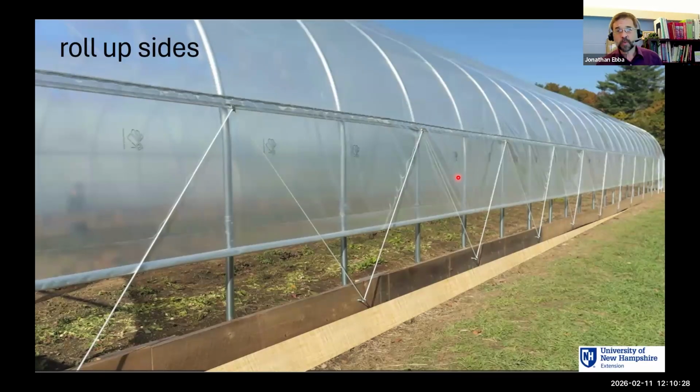One way of thinking of that is 20%. I see 20% of the floor space. I see Vern here. We had a great conversation about this earlier, and we all kind of agree that if we're looking more, the bigger the better, right? And so 35% of the total floor area would translate to 5 foot 3 inches of open space on a 30 by 96. So we want to make sure we're getting enough open area that we can affect meaningful air exchanges when it's hot.